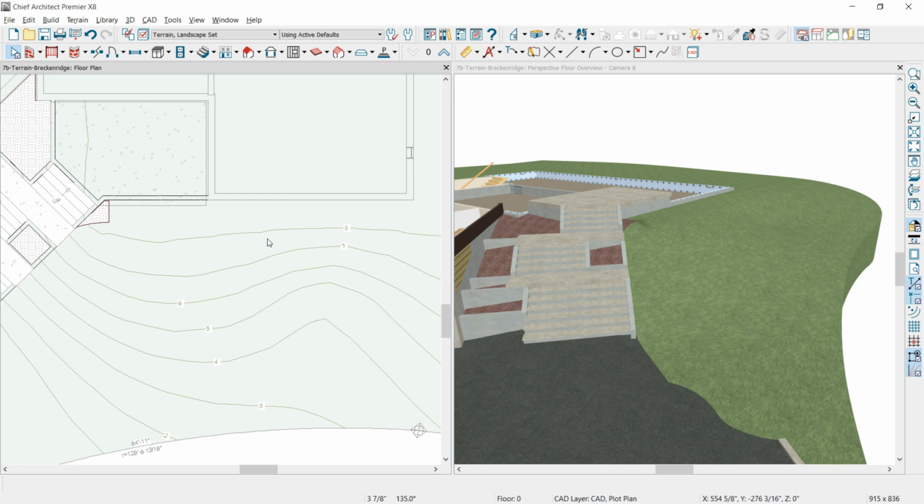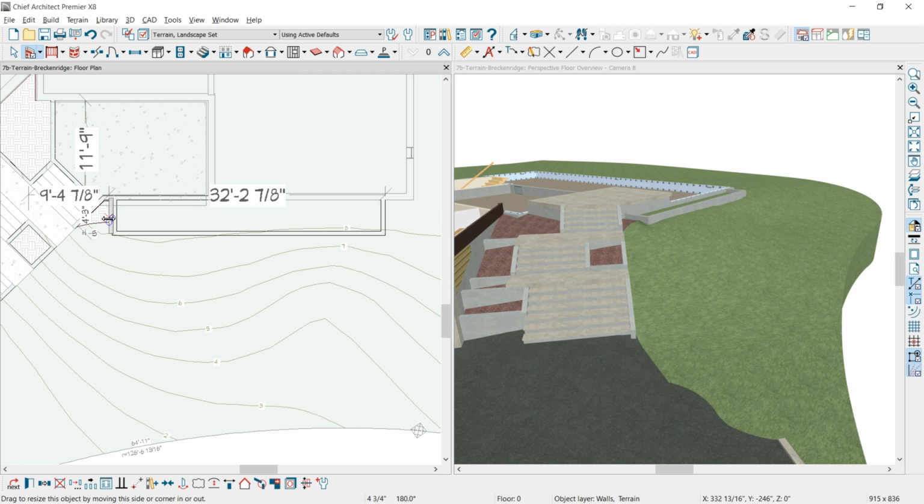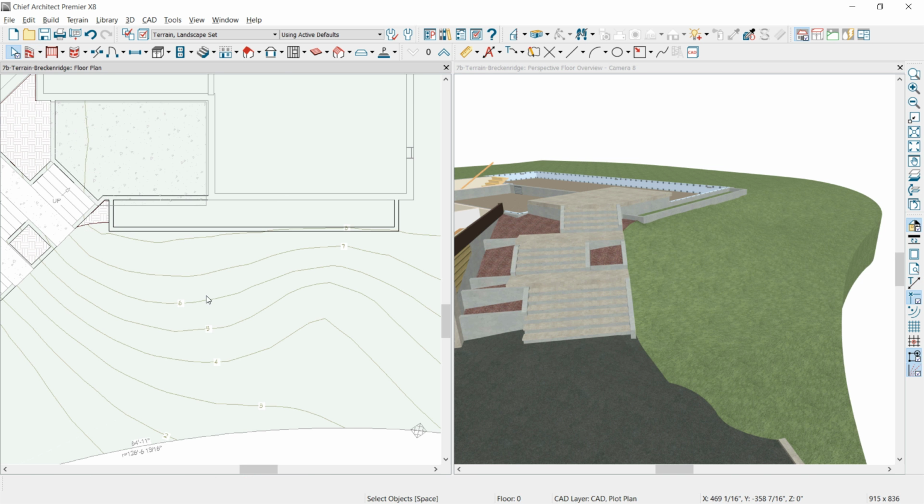I'm going to begin by creating the walls using the terrain walls for the reflecting pond. My default wall type is still using that terrain wall. I'm just going to come in here, drag out the walls, bump that to our terrain bed, and let that form the area for the reflecting pond. I'm going to end up pulling those walls up a little bit higher so that the water is even with the porch or near even, so it looks like an infinity pool coming off.